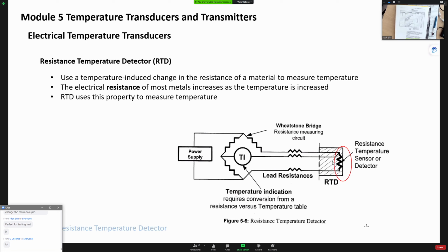So this is the resistance temperature sensor. We have another fixed or changeable resistance value to build a bridge down there. Then by measuring this voltage down here, when we give a power supply, we can, based on this voltage, convert it into the temperature measured down here.